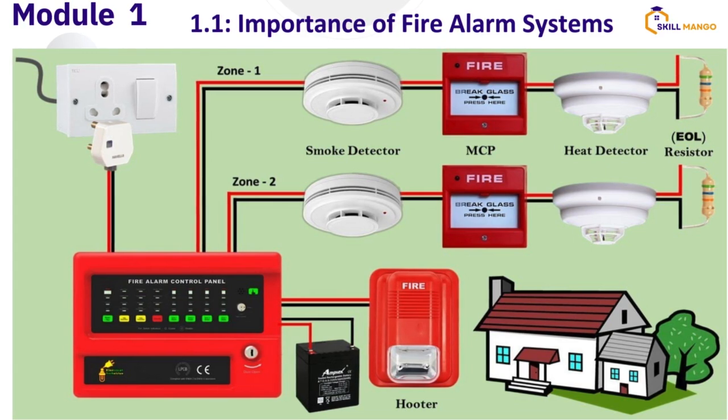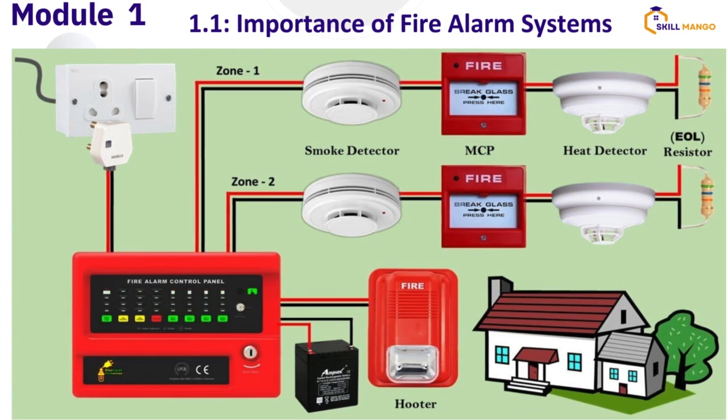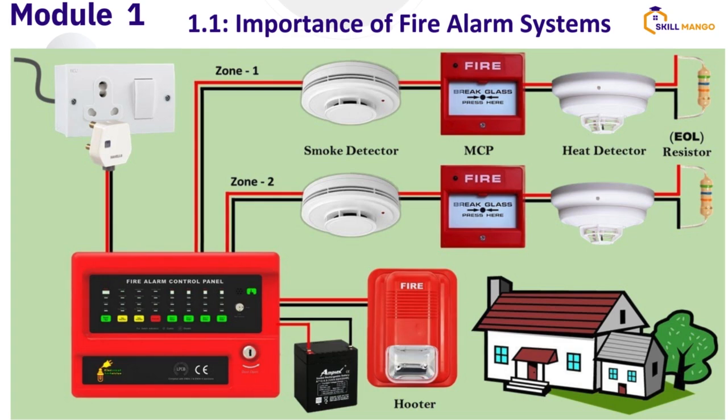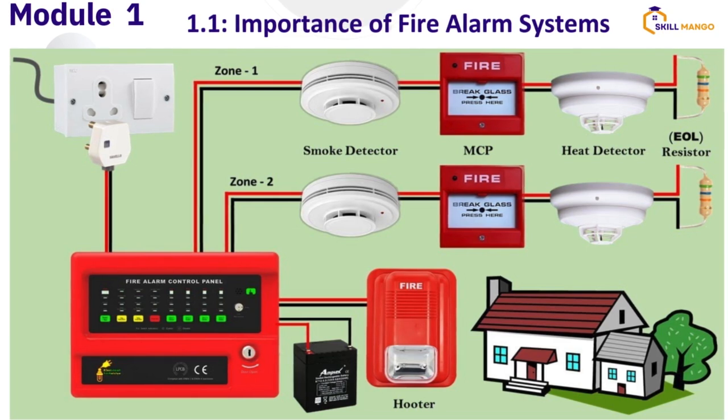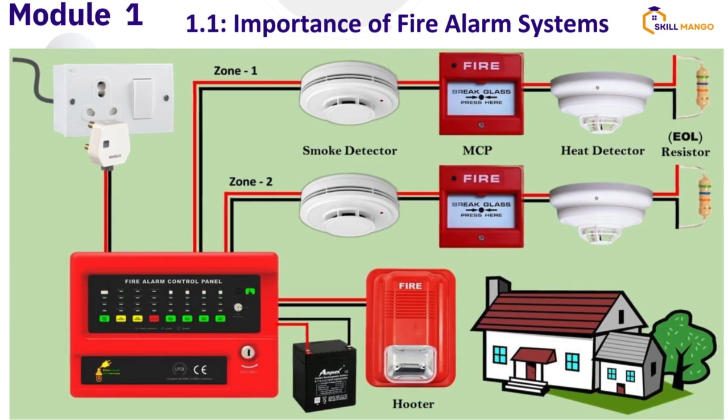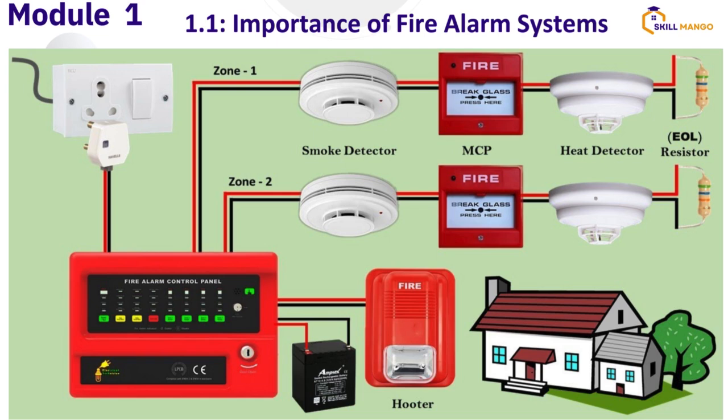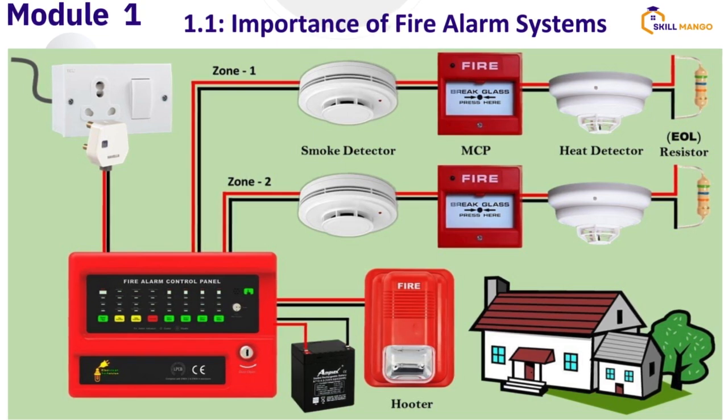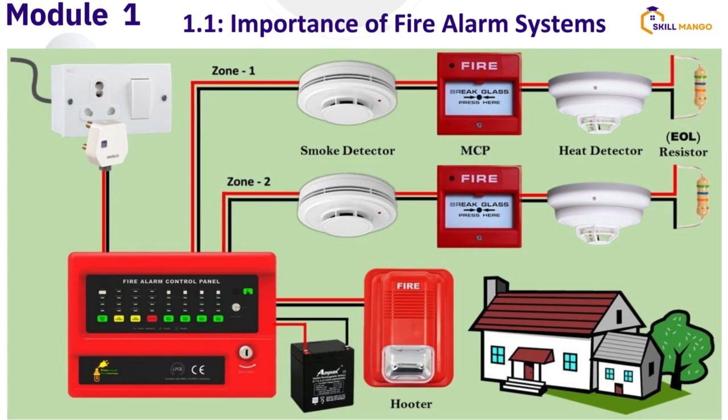It's not the best, but it's better you use the fire resistant cable. If you can't get access to that particular cable, you can use the red and black 1.5 mm pure copper original cable. That will also serve. Then you do your chain connection, and at the end of the line, you put your end of line resistor. So basically, that's the diagram.